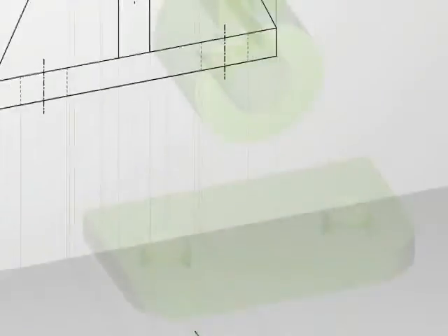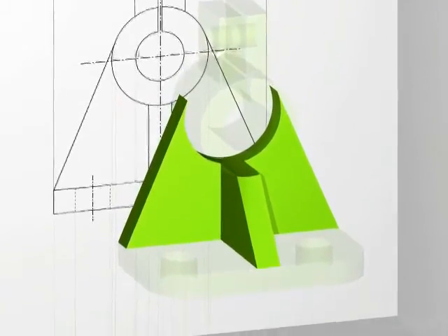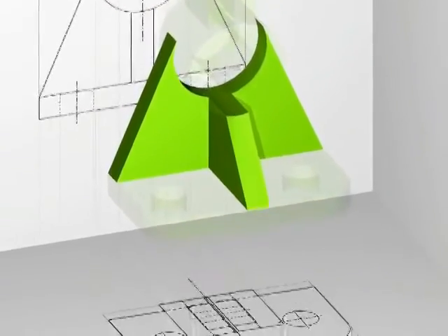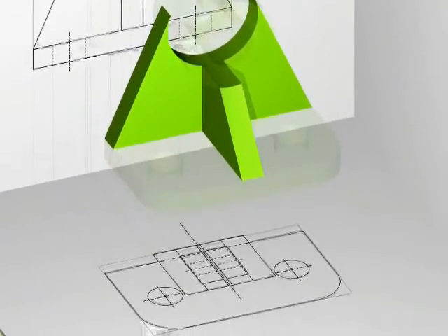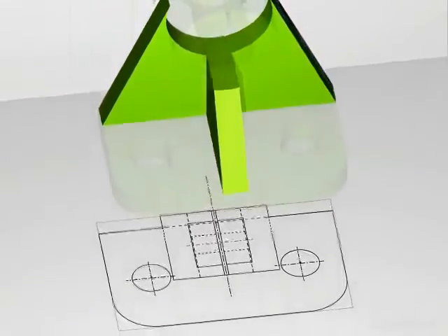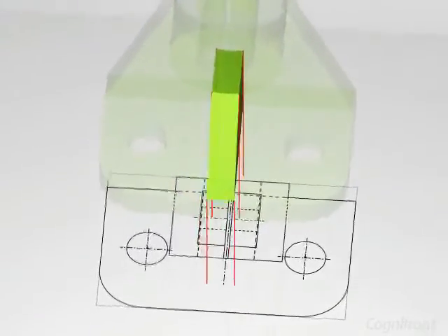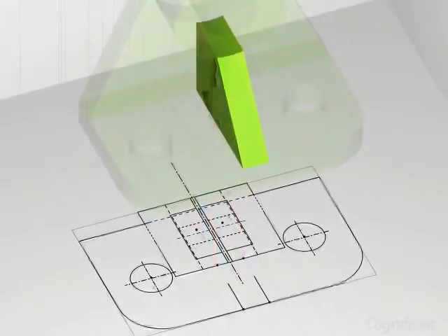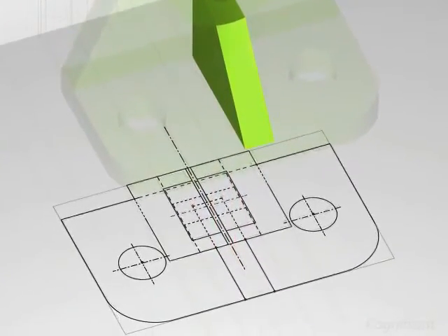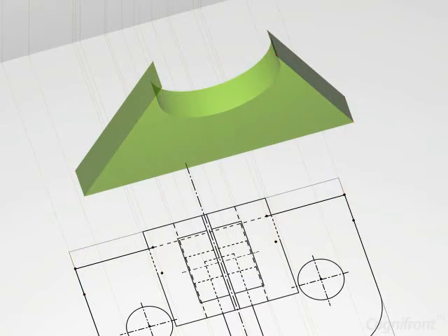Complete the top view by drawing the ribs. The ribs are connected between base plate and the cylinder. There are two kinds of ribs in this object: supporting rib at the center of a cylinder and tangent ribs on two sides of the cylinder.